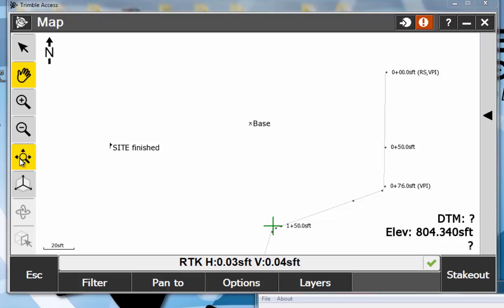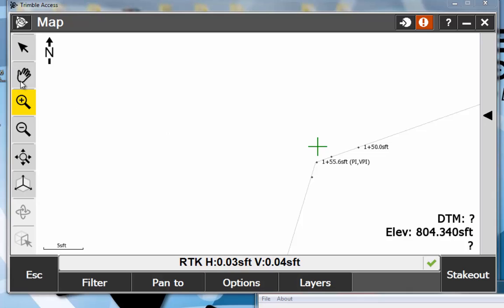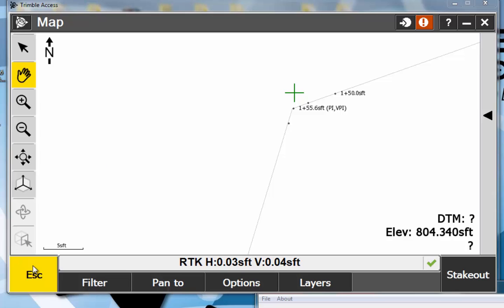All right, so here we have our storm, our pipe run. Notice we have a few different things: the invert in, the center invert, and the invert out. Those are the three points you defined. But we don't have our center of structure on here. I can stake this out easily, just station and offset like I'm used to. The invert in, center invert, and invert out are all defined positions on my alignment that I can navigate to and stake.